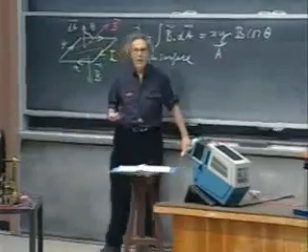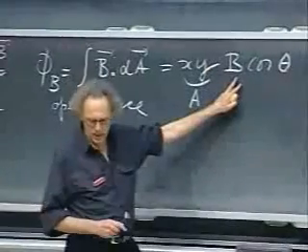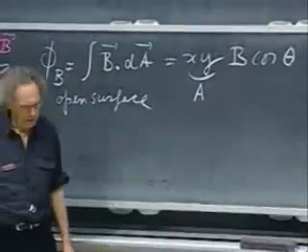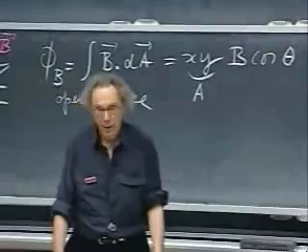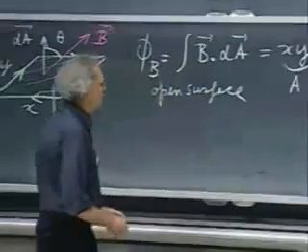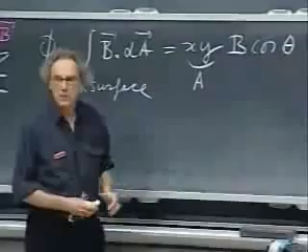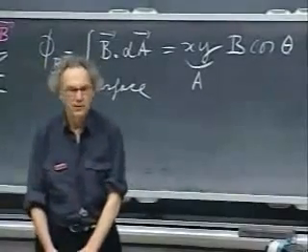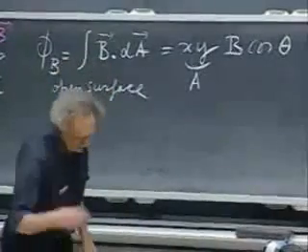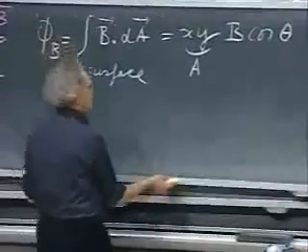Last time, I did several demonstrations whereby we changed B. We had dB/dt's. And there was one particular demonstration that blew your mind and that you will tell your grandchildren about and that you will always remember, I hope. Today, I'm going to change theta and I'm going to change the area, which will also give me induced EMFs and therefore induced currents in a closed conducting loop.